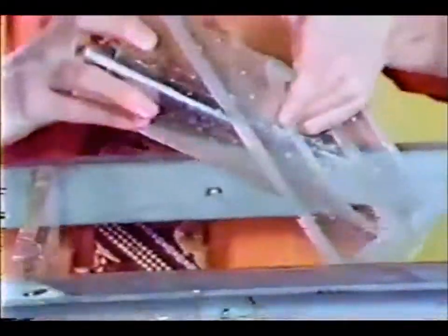The area of the mitered entrance is larger than the thin edge projecting. Therefore, you would expect a lower headwater elevation. The headwater hasn't changed very much, indicating that the effective flow area is about the same. There is not much improvement with the mitered inlet, and it requires a headwall for structural strength.